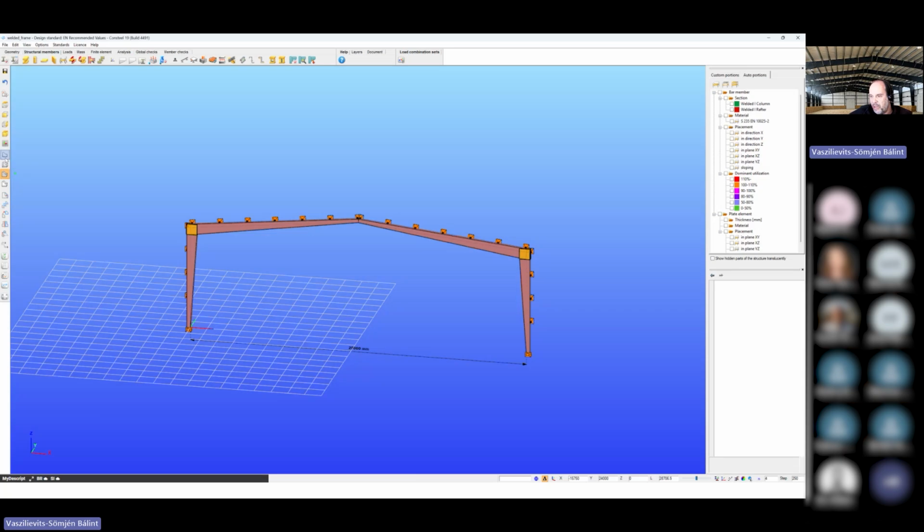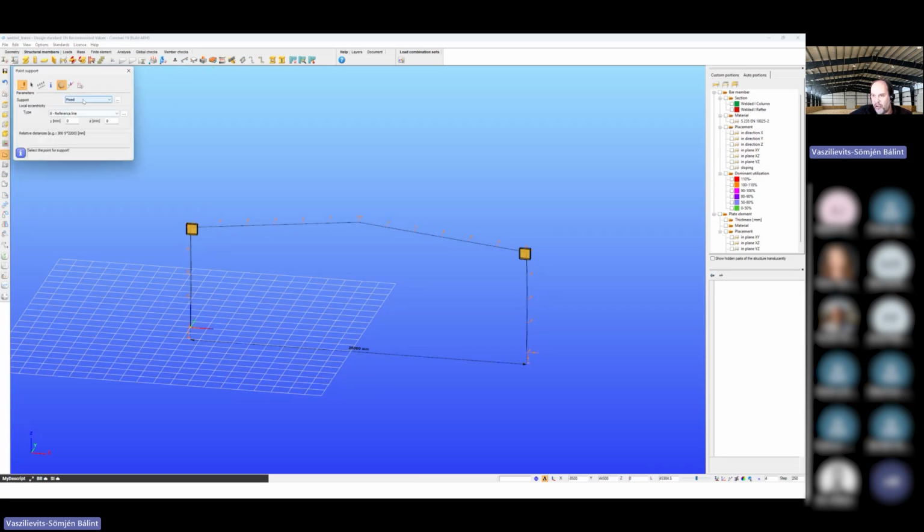What is very convenient in metal building practice is to use so-called flange braces. At the moment, for simplicity, I define infinitely rigid out-of-plane supports, although this is probably not the reality. We had several trainings. We will also repeat it later on when I speak about that. It's very important not to automatically make the simplified modeling. Simplified modeling might be unsafe.